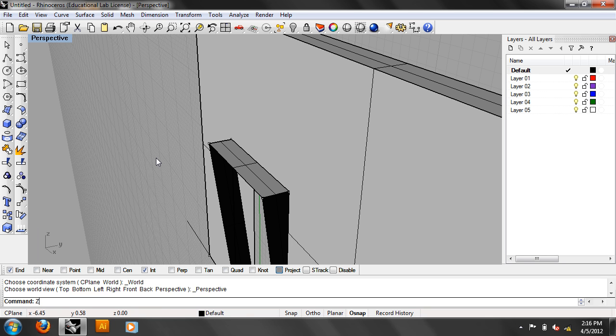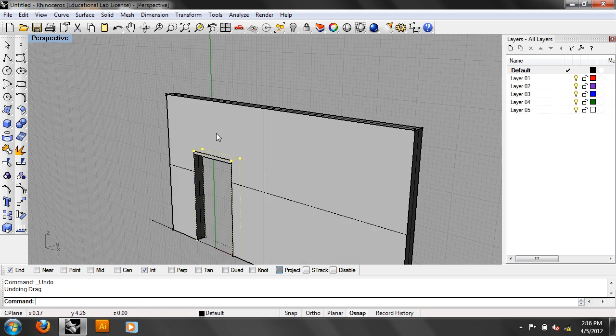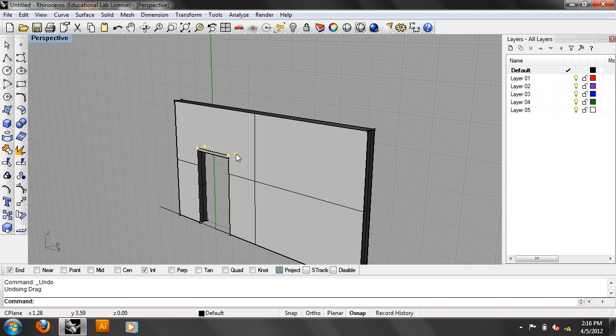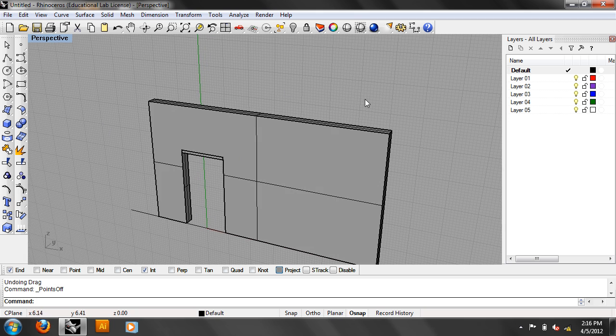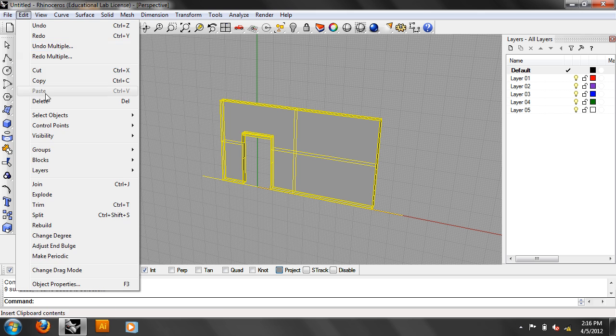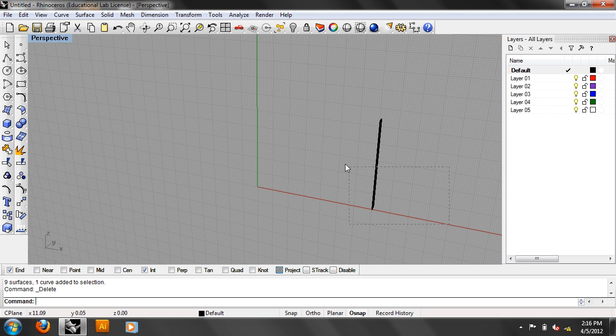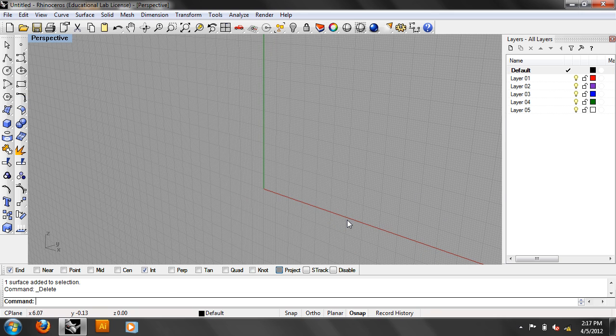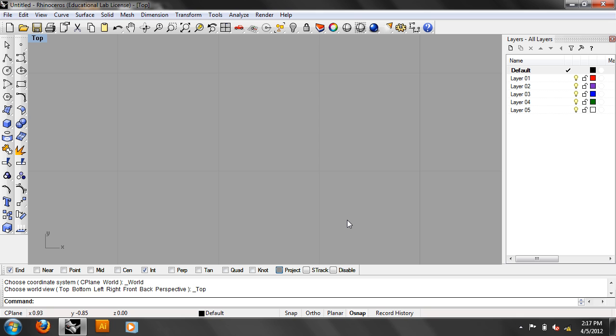Then when you're done stretching, once you get it stretched properly, you just join them all together, and that will actually recreate your solid. I mean, you turn the control points off by right-clicking and then join them all together. Okay, it's tricky. It's unadvised. There's no easy fix, but it is possible, and that's why I don't want to just be dogmatic. It is possible. Okay, so, any other questions? That's a great question about that model, though. Any other questions? No? Okay.